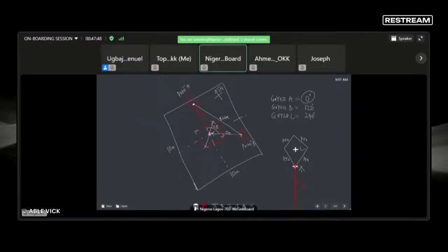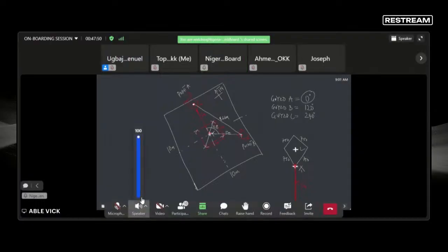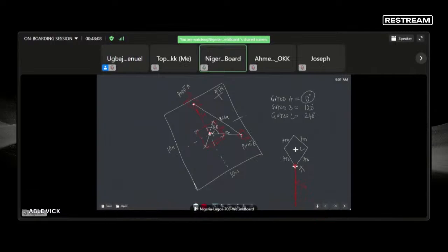So, how do we get the third guide wire point? Exactly. So from point A, one person stands at point A, takes his tape to 8.66 meter. Someone stands at the middle of the tower, takes his tape to 5 meter. Force the two tapes to intersect. Wherever they intersect is your 120 degrees. So we'll be having something like this.